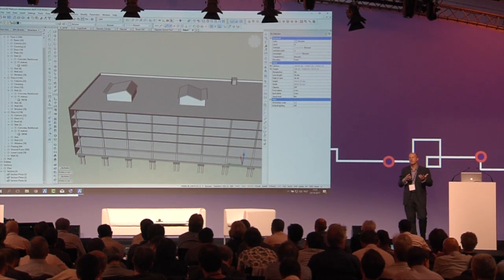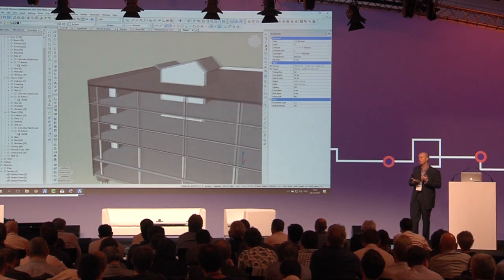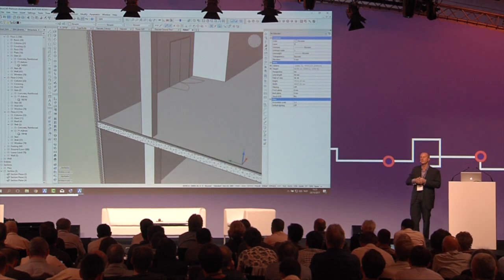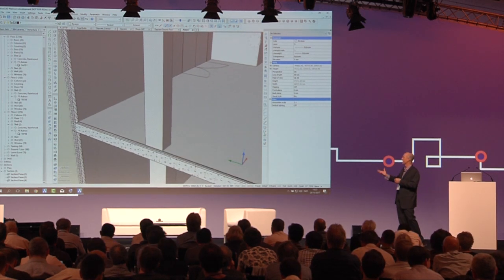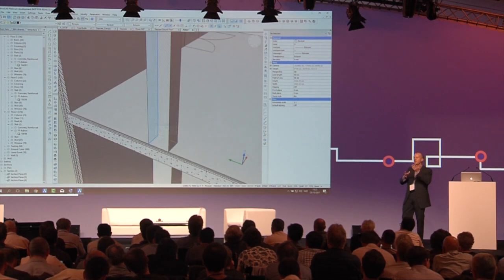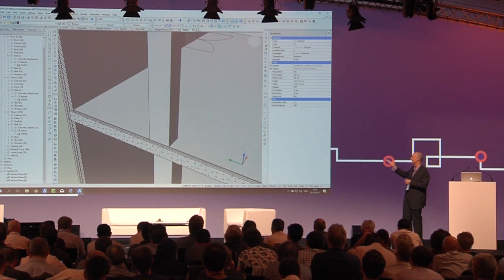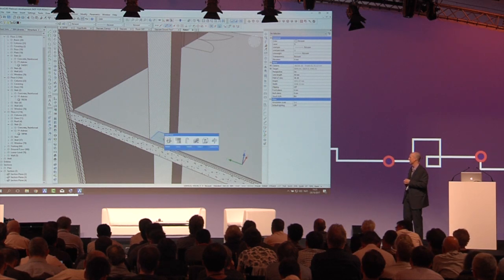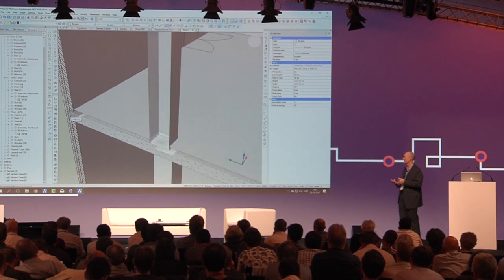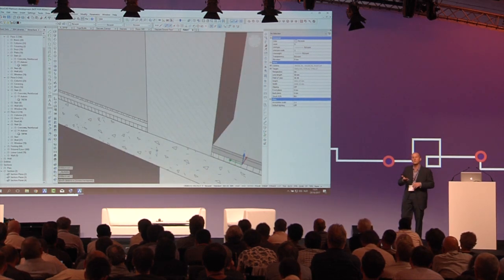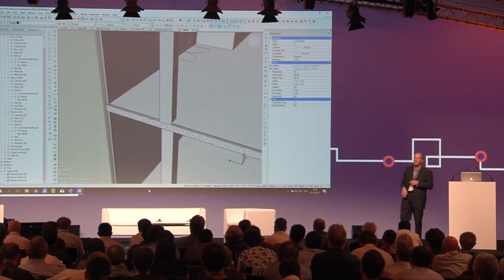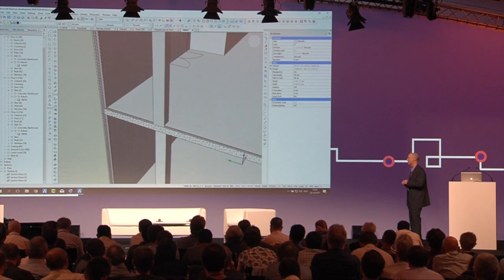We'll go to where a column meets the floor, and we'll show a simple way of how, we say direct modeling, and the other ones that we'd shown, Jacob had already made the updates to it, but all this is doing is if it's walls, you're picking the surface of the ply and dragging it down. In this case, it's a column, and we can just drag that face using BIM drag it down into the floor, however many plies that we want to go through, we can do that. And in this case, again, it's just connecting to the structural ply of that floor.